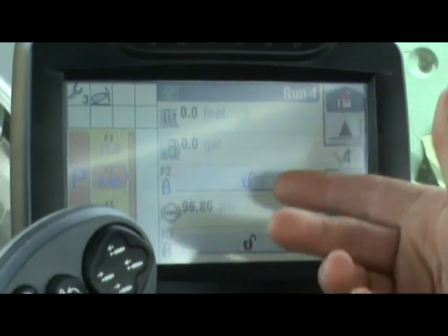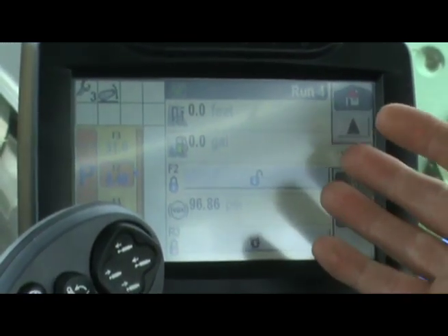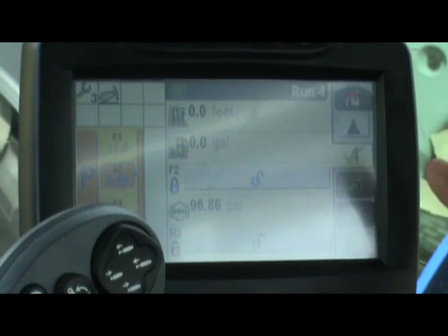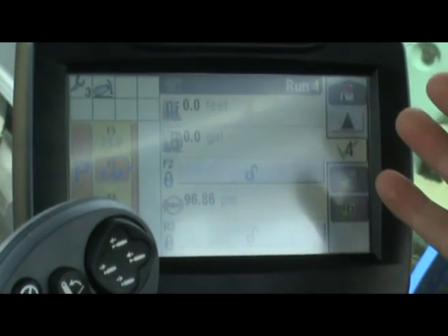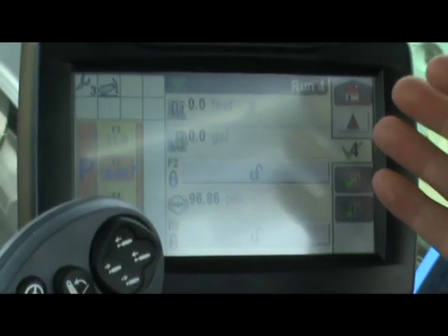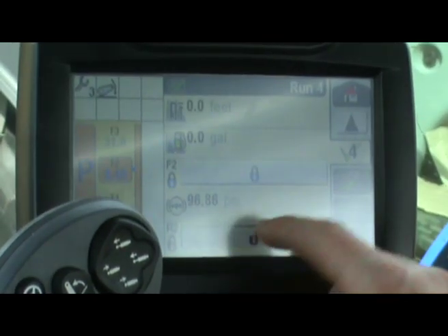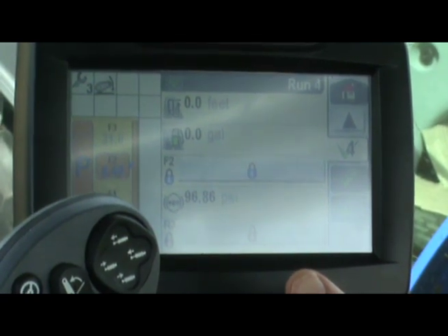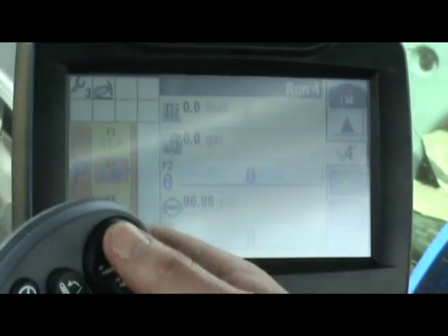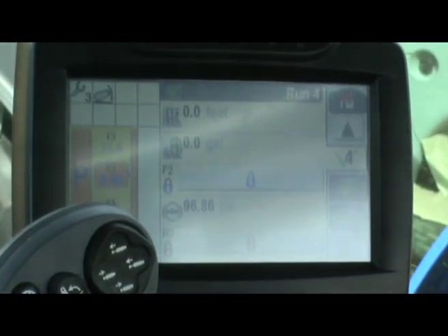So this one's a good one for, say, if you're doing road work, got a trailer on the back, tractor's doing a lot of silage hauling. One thing I might accidentally do is unlock the tailgate. So here, tapping that locks the tailgate up, tapping that locks the lift ram for the trailer as well. So you can't accidentally press a button and tip the silage on the road.